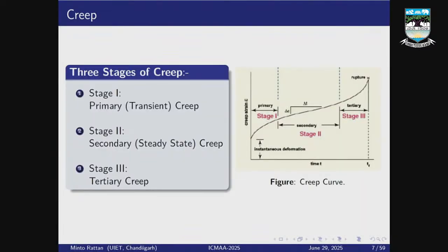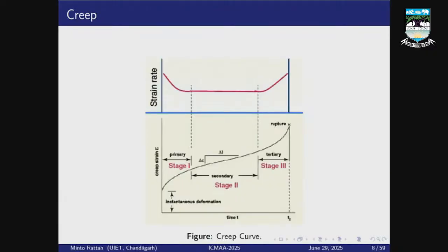When metal matrix composites are tested under creep conditions using tensile or shear configurations, it is usually possible to identify the standard three distinct stages of flow within the creep curve. One is primary creep, the second is secondary creep, and the third is tertiary creep. A creep curve is a plot between the total creep and the time for the entire duration of the test.